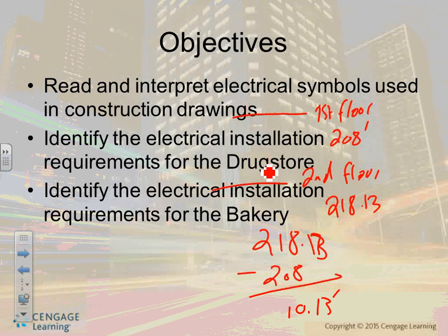But where are they drawn? Right underneath it, we say A, it's A6. So A is the section number, and A6 is where section A is drawn. Revit, I believe, uses numbers there. So you'll do section 1, and underneath it E5. So section 1 is drawn on E5. Yes, sir.